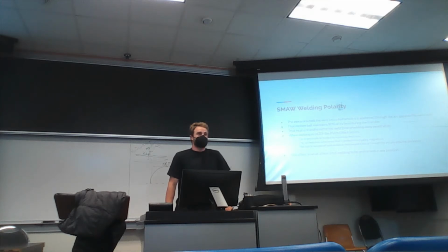And that also can be true in wire feed. However, that gets into the modes of transfer, which will be covered in later lectures. Just so you know, there are 3 different modes of transfer, or I guess technically 5, but 3 main modes of transfer that are used in wire feed, which are globular, short circuit transfer, and spray. And some of those can be done in all positions as well, due to the pinch effect.